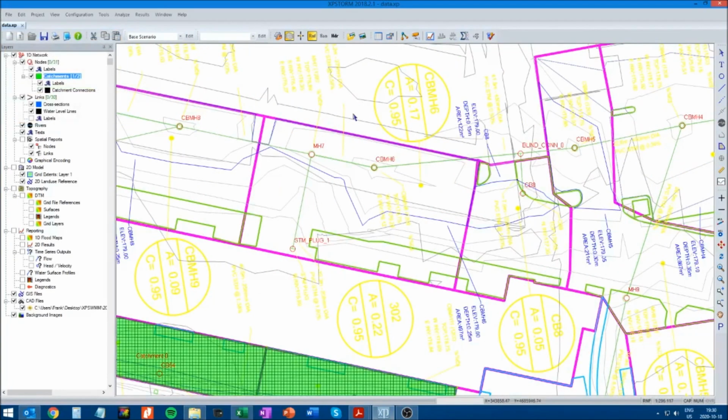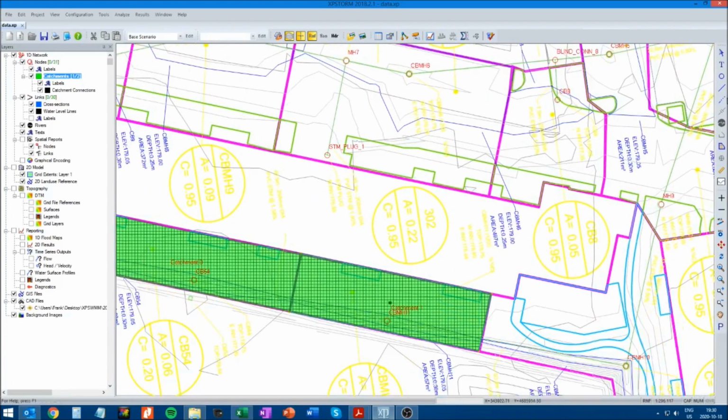So now it's actually better to pick the snap on, because if the corners of the catchment areas should match the corner of the adjacent area, then it's better to have the snap, and that way the same point is selected. Otherwise you will have to go to each node, each corner of the catchment area, right click on it and pick weld vertices.